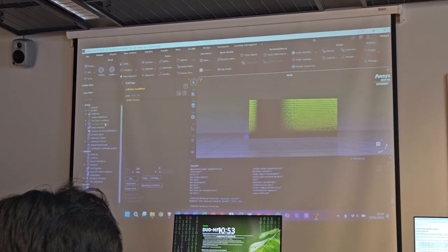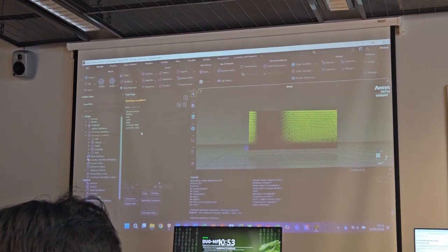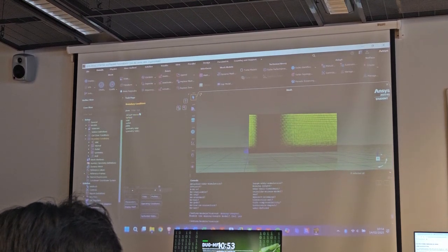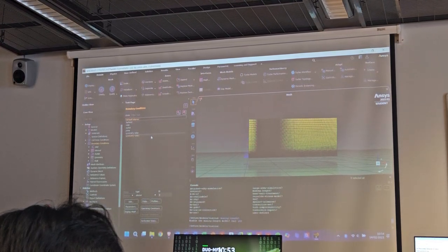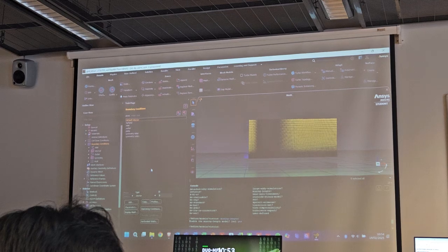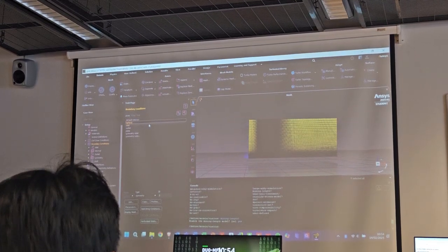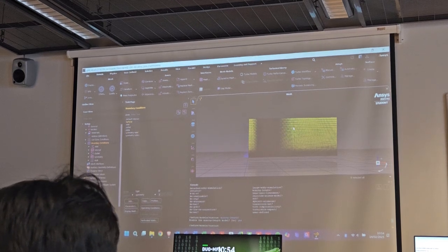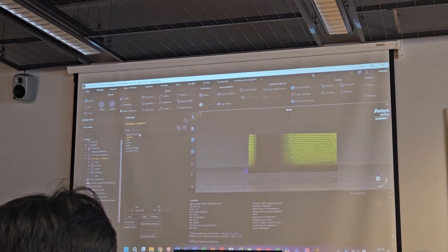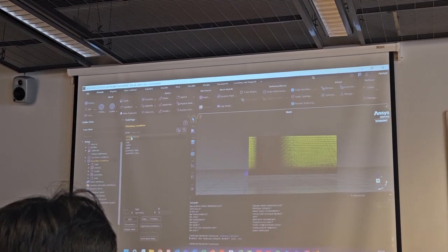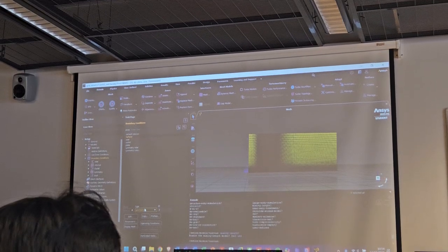Next, we can double click on boundary conditions. Here we have different surfaces, so let's start from the top. There is default interior. This is an interior type, so it's not really a boundary condition. We can leave it as it is. Then we have the far field, the surface on the top. We said we can set this as a symmetry so that it doesn't affect the flow. It's already type symmetry, and we are fine with that.